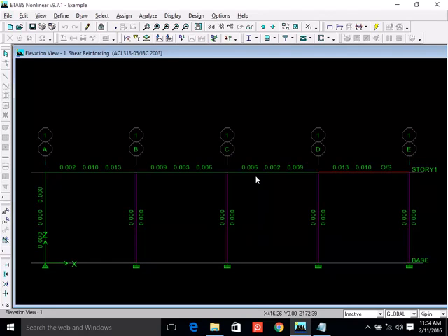But you have to check it. Check for s maximum. You know, shear reinforcement has a limit. No, I think they call it s maximum, not s minimum. This all has to be checked in the manual. What will the maximum be? Yes, it's d by 2 I think. Actually there are different values. Yes, at least you should have that. 300 millimeter. Or at the most you have that spacing.